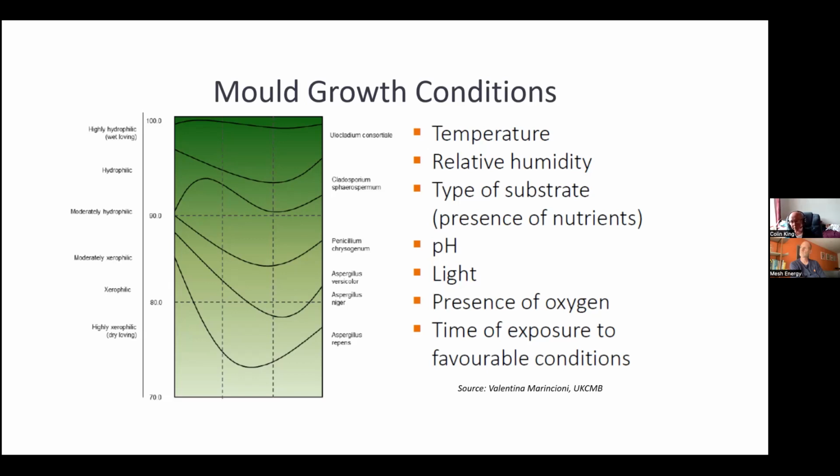It's not rising damp. It's the fact that the water pressure is too high at the base of the wall of the structure. It's only ever rising damp if you have the presence of hygroscopic salts. And even if you do a calcium carbide test, all that does is measure absolute moisture. It doesn't tell you about hygroscopic moisture and hygroscopic salts. So the only way you can do that is you would have to do a calcium carbide testing, and then the sample would have to be oven baked to find out what of it is hygroscopic salts and damage from hygroscopic salt moisture, and how much of it is actually rising.